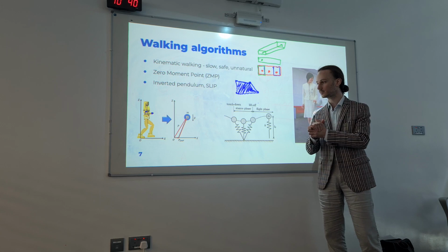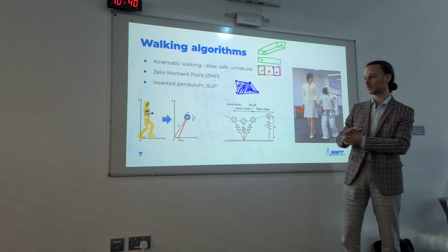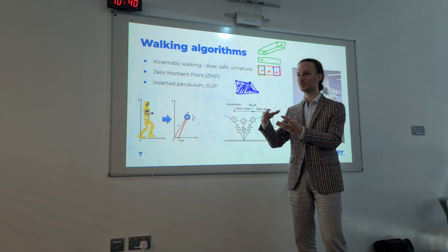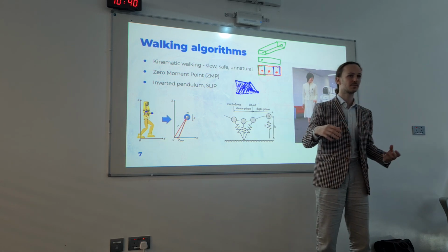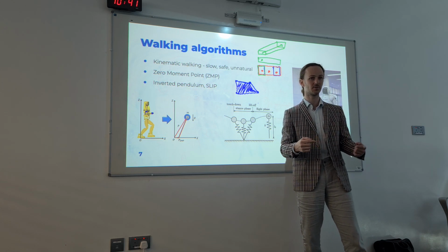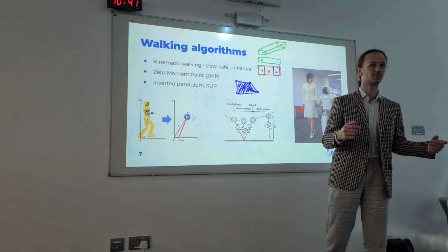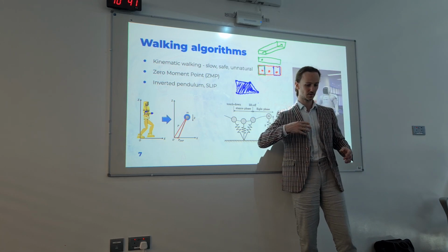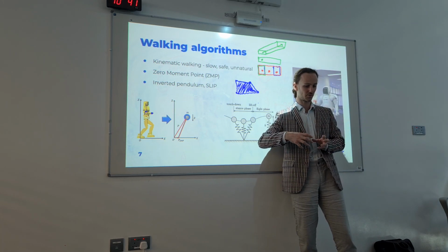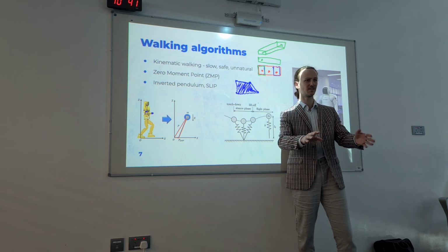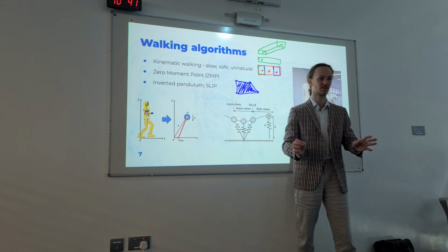And the meaningful enough abstraction is really the inverted pendulum. So if we consider a single stance phase between the switching of the legs, it's really the inverted pendulum in 3 dimensions. And I have to go through a certain trajectory that looks suspiciously like a sine. It's not exactly, but something like this.